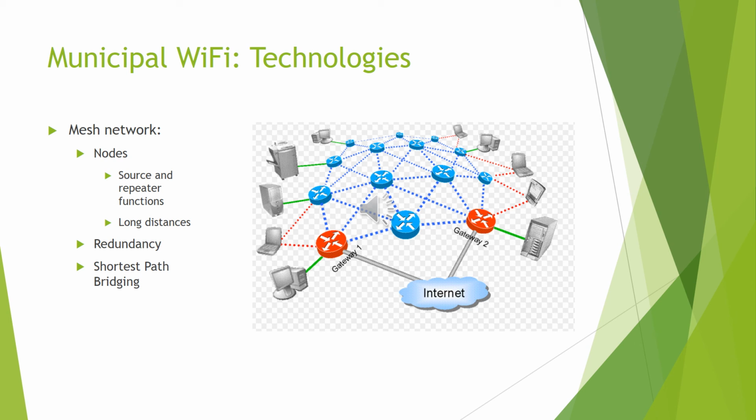As long as a node is within the suitable distance from another node, they can connect and relay information. So, a mesh network provides network redundancy throughout the system. If one node fails, it can connect with the next nearest node and proceed forwarding information. Mesh networks are self-healing in this sense. While individual nodes must be close together to transmit information, the entire system can have considerable range depending on how many nodes are used and the bounds of the system.